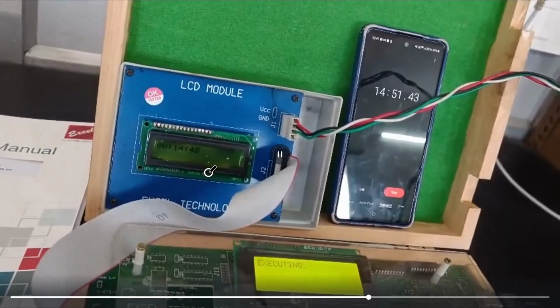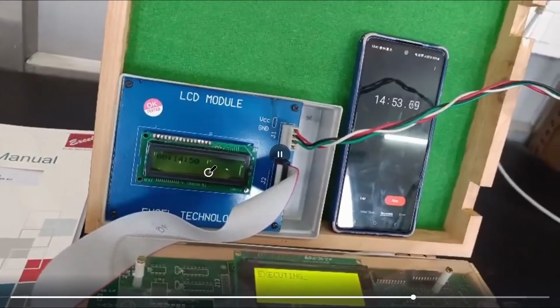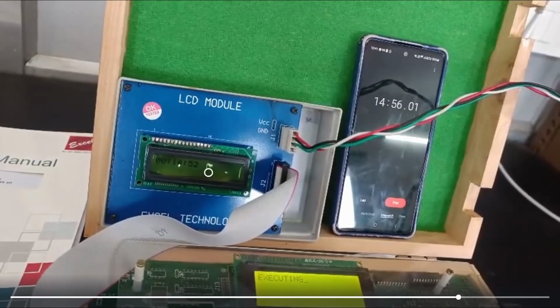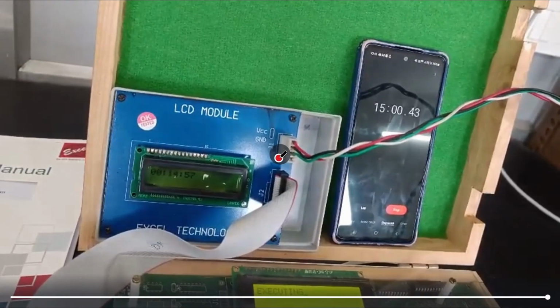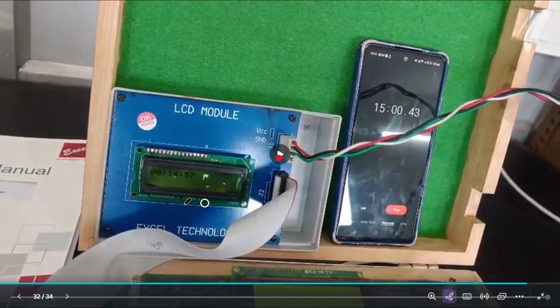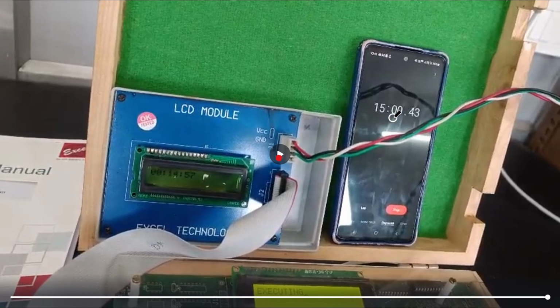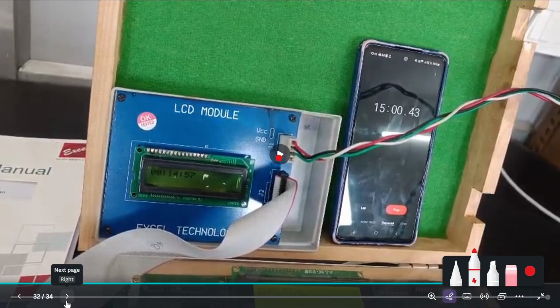The LCD is working fine as a clock. However, there is an offset of 2 or 3 seconds, as you can see. When we pause it exactly at this moment, it's at 57, and this has crossed 15 minutes almost exactly. So this means we have a delay of around 3 seconds for every 15 minutes roughly, and with this information we actually calculated the actual clock frequency of the crystal in the last 2 slides.